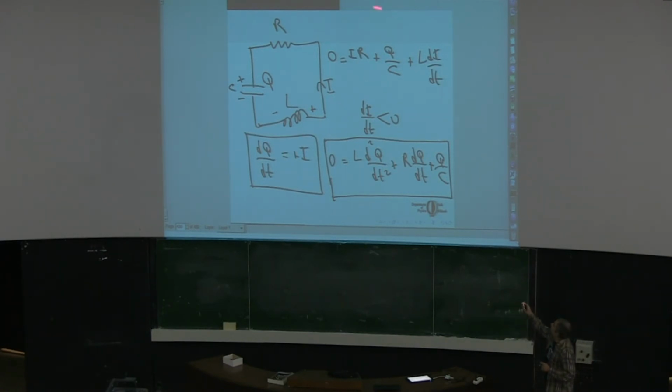So if we are writing this equation, if we are writing the potential drop of the charge, as we go from here to here, the potential is increasing because this point is at the positive terminal. But here both of these terms are the potential drops. So we have to write a negative potential drop as we go from this point to this point. Now, L di by dt is already negative because di by dt is negative. So this term is negative. So by adding this term, we are writing a negative potential drop.